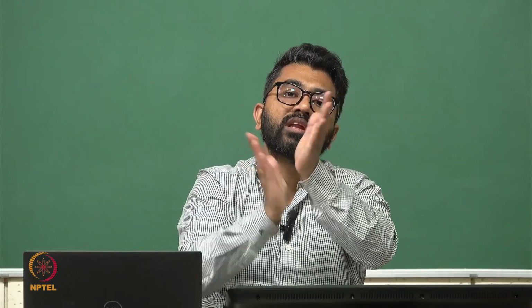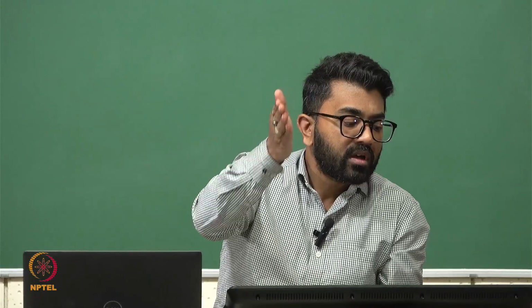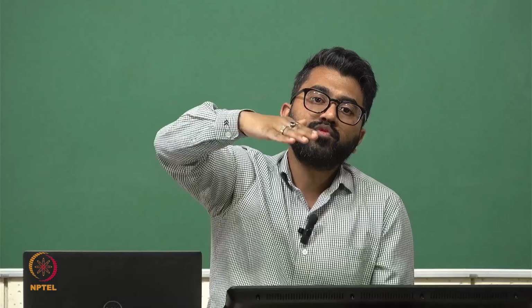Whenever I stretch this entire model, it cannot be that the fibers and matrix are stretched in the same way. They have different properties. So the fibers will definitely get stretched in a different way, and due to that difference in stretching of the fibers and the matrix, you will see the fibers rotate by a certain angle from their initial path. Let's say the initial direction of the fibers was towards the direction of the loading. Now when you have applied the loading, it moves by, let's say, 25 degrees. This is the interaction effect between the fibers and the matrix.